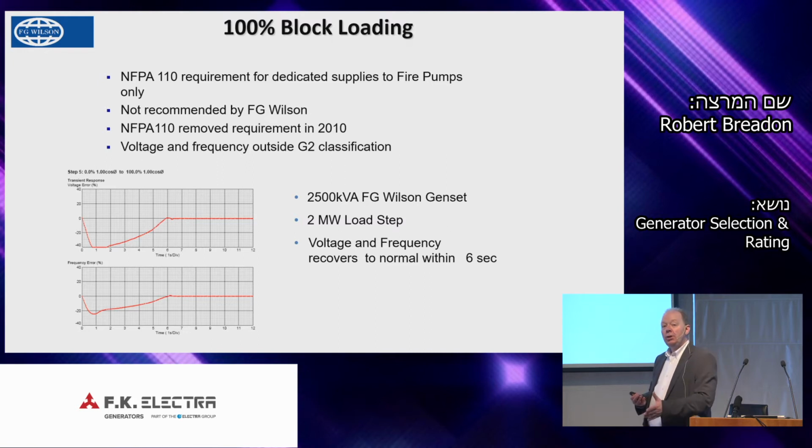When you place that amount of load on at one go, it's just amazing how it can actually respond. So again, what we're doing here is removing with the voltage slope, we're taking voltage off with the frequency fall off, and the engine actually eventually will stabilize and return. I think still it's a very hard thing to do on your brand new engine, but some customers insist on it.